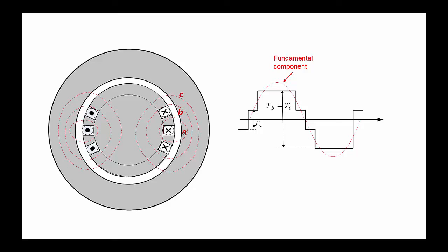All I wanted to do in this presentation is to start with Ampere's Circuit Law, very simple, that you all remember or should know from physics, or if you didn't remember it, anyway, I revised it today. And from that, we moved into magnetic circuits and started modifying the magnetic circuits a bit, and then we found the construction of laminations in machines, and then we decided to distribute the winding, and we found that we can distribute the winding in slots. These slots can be either on the rotor and the inner cylinder or the outer cylinder. And we will discuss this in detail later.